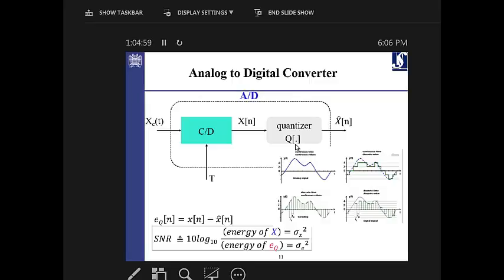For the speech case, if you use these capacitor-based microphones, they are between 0 and 5. When they output any signal, it's between 0 and 5, and it's completely matched with every A to D chip that you use. But inside the A to D, because of the importance that one level has with respect to another level, for example, the higher levels don't have that much importance, but something between 0 and 3 includes most of the information, they exponentially compress it, and that's called the A-law or mu-law standard.